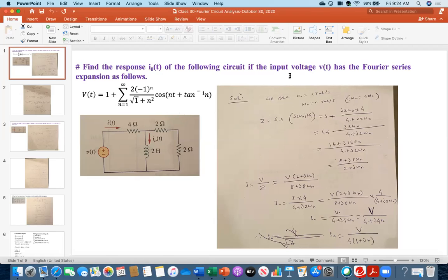With the Fourier series, for example, at your home you have a load, for example an air conditioning load, that is consuming power. You look at the voltage or current profile, and you might see that it is not purely sinusoidal. There are some harmonics in it. If you analyze that current with the help of the Fourier series, you might see this type of representation.